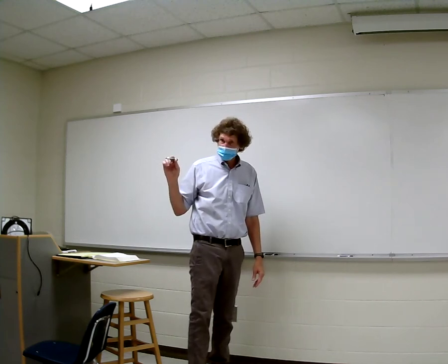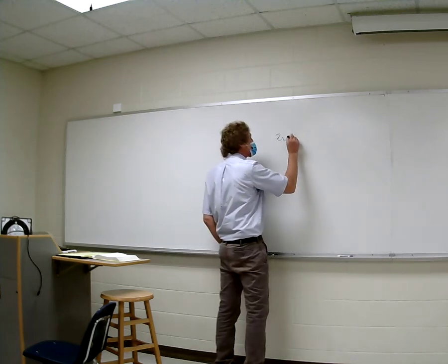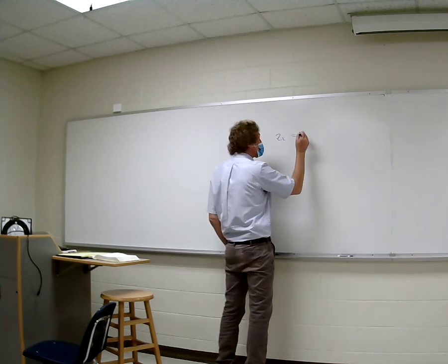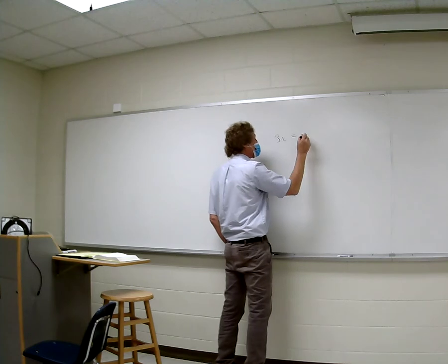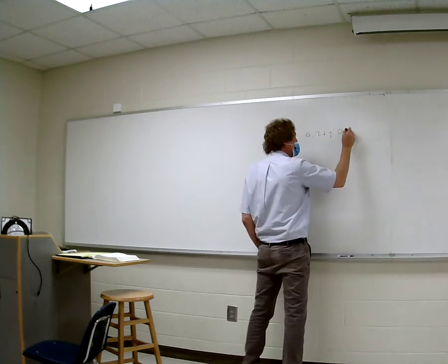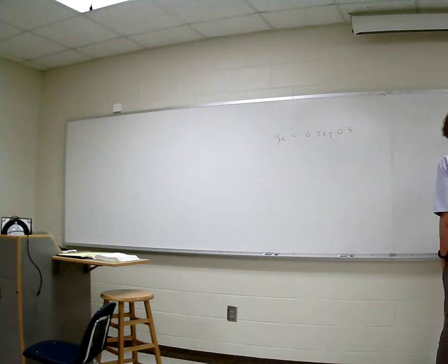Whatever you add to get back up to 0. Is that 0.2 plus 0.8J? Oh, yeah. 0.2 plus 0.8J? ZL is, oh, that's the normalized. Normalized. All right, yeah. So small z_L is 0.2 plus j0.8? Yes. Okay, I'm going to try to sketch freehand a rotated Smith chart.